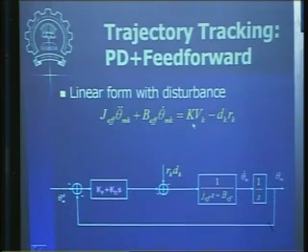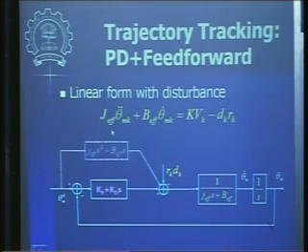So those effective forces, if we pre-compute and feed in our control law, then it becomes a feed forward control. This is a block diagram of our standard PD kind of a control. Now we compute this feed forward term, based on the theta d desired motor position.